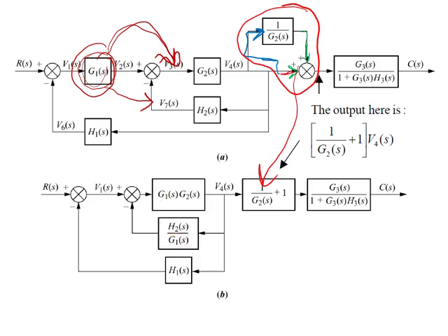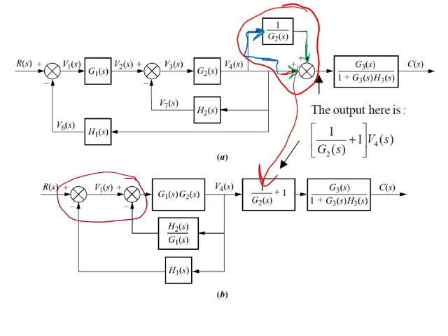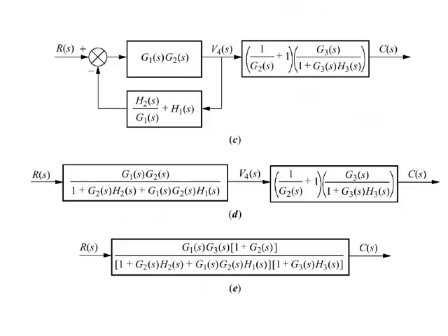Now things are getting simpler. Why? Because here I have these two summing junctions, and we can join them as one. So if I join them as one, I will find that this block with this block are parallel. When we parallel them, the result will be fed back with this. See the next slide. So here is the cascade of what he did of those blocks. It was very clear. Then he applied the parallel rule to these two blocks, and it results in feedback.